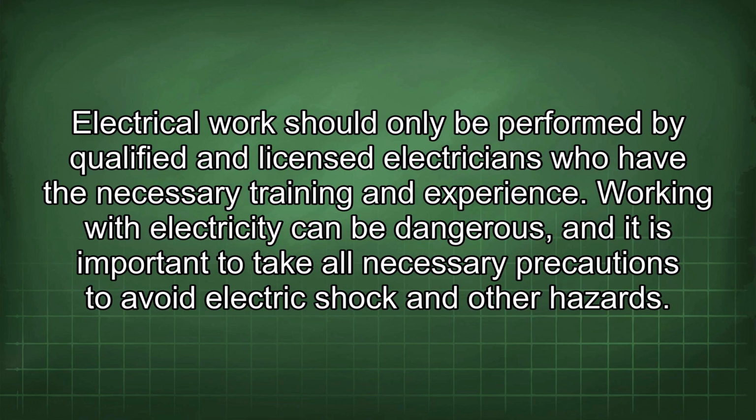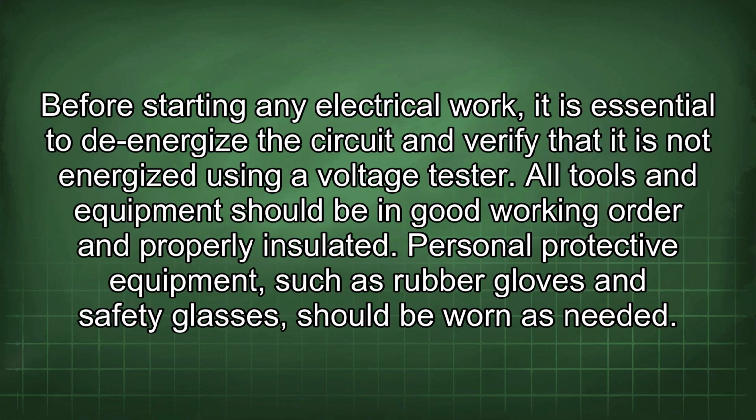Working with electricity can be dangerous, and it is important to take all necessary precautions to avoid electric shock and other hazards. Before starting any electrical work, it is essential to de-energize the circuit and verify that it is not energized using a voltage tester. All tools and equipment should be in good working order and properly insulated. Personal protective equipment, such as rubber gloves and safety glasses, should be worn as needed.